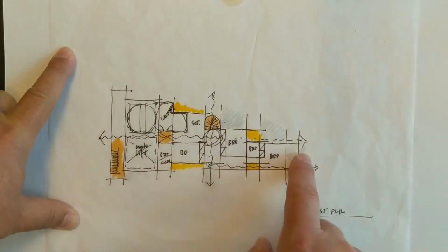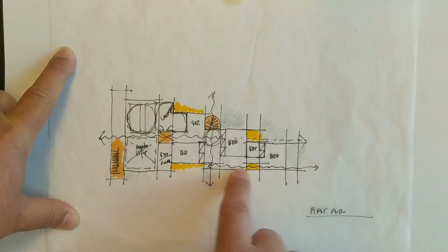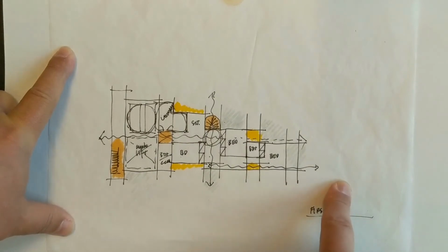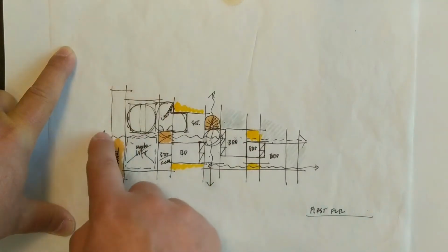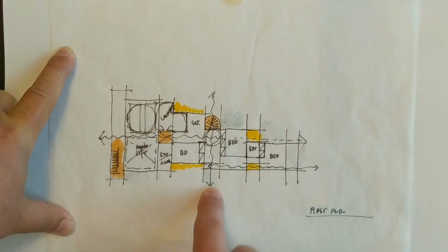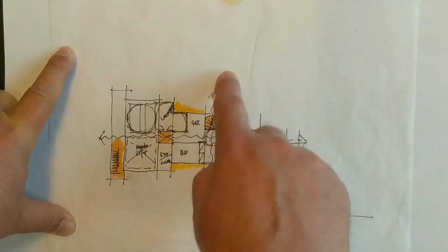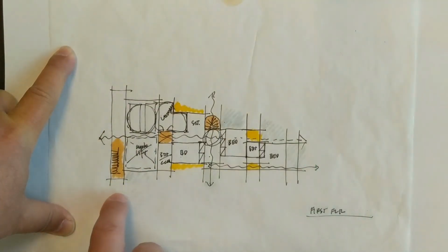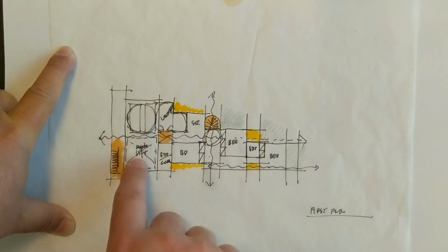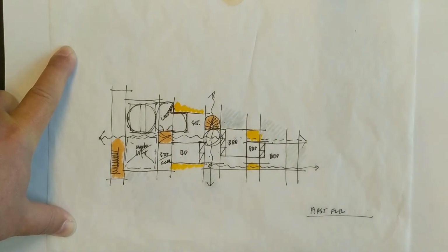And this is one of the designs or sketches that I came up with, which basically has the floor plan, a wedge that steps away from the property line, following the property line. This one steps back just a little bit, but more or less maintains a straight wall on the street side. And what you can see is I have some thoughts about how the circulation moves through the building, so that there's a central hall and circulation this way and then circulation this way, with all of the major rooms facing the backyard, which also has a great view. And then I've divided it up into service spaces and useful spaces. So we're setting up a structural system that's also a spatial system.